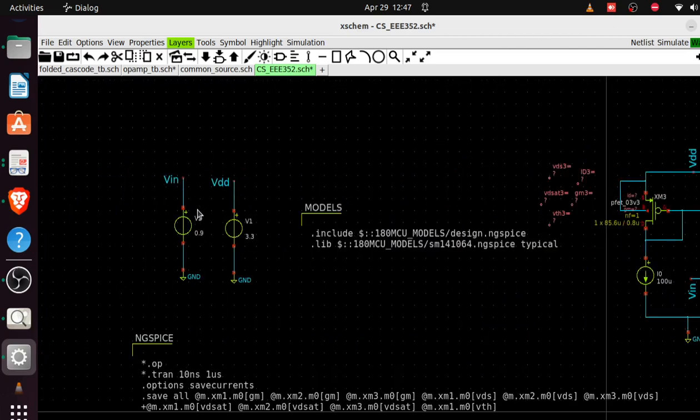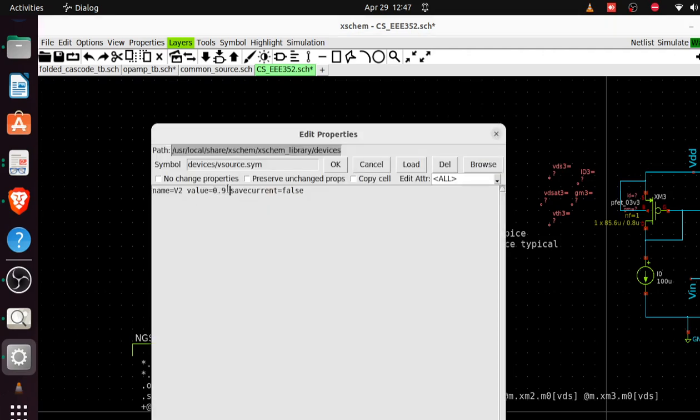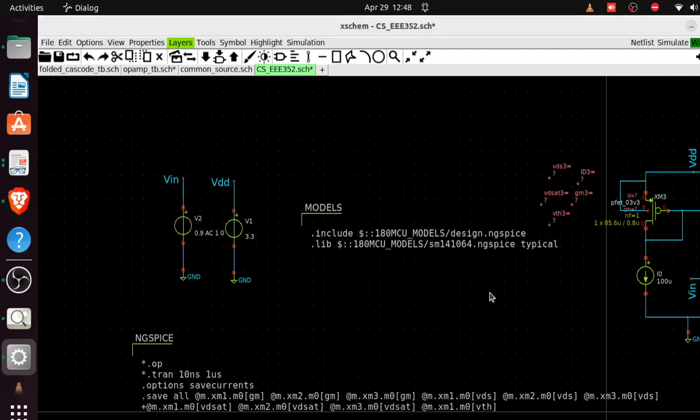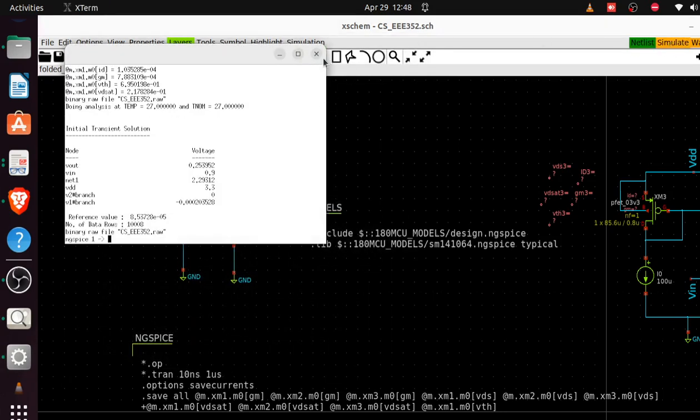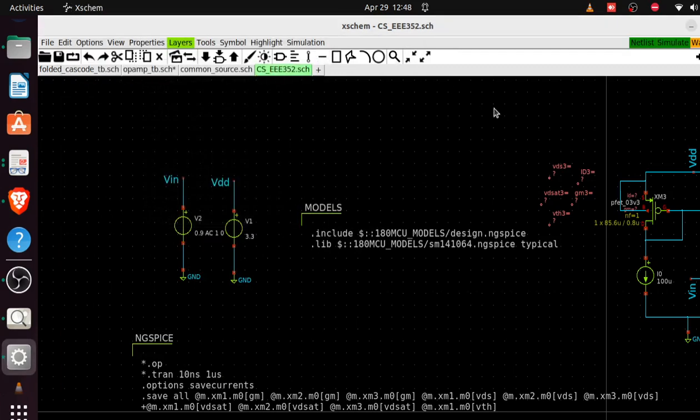So what's the thing? You want to do AC analysis? Sorry, you have to edit this input voltage source. I'm going to add 1 0 space 0, then quotation marks, everything in quotation. So I think with this everything should work fine. Sorry for that. So Control S, save again, start all over again, hit the netlist button, then the simulate button, then hit the wave button again.